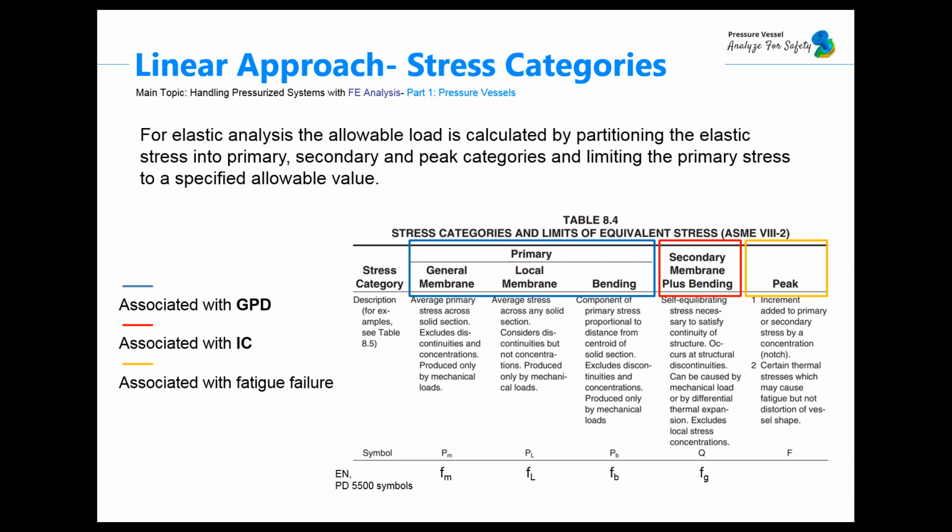Elementary stresses are calculated at all points that are in scope of the analysis. Okay, this is what I wanted to say. In a three-dimensional case, these elementary stresses consist of a vector of 6 components of normal and shear stresses, which finally should be classified as membrane or bending stresses.